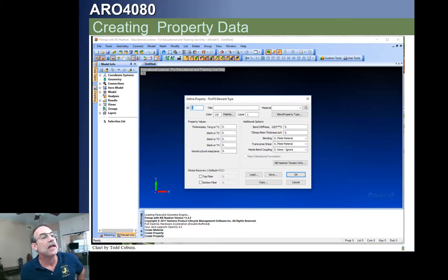So then, if you wanted to put in a parameter of different bending stiffness than 1/12 t cubed, then you would do this in this bending stiffness parameter. Or if you wanted a shear parameter, you could put it there. Mostly we're going to leave those 0. Now remember, if you leave the bending, transverse shear, and bending-membrane coupling blank or 0, then what that does is you will only have a membrane with only axial and shear capability. That's what we're going to do mostly.